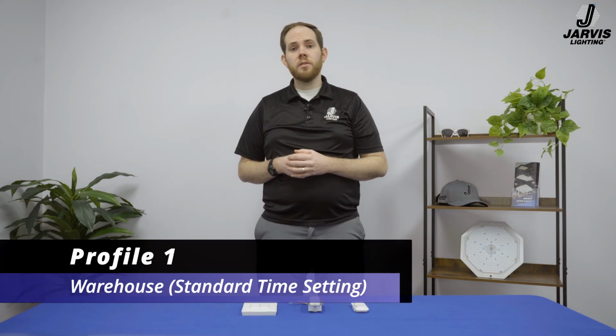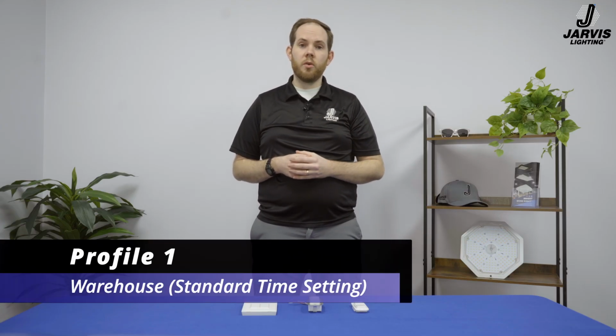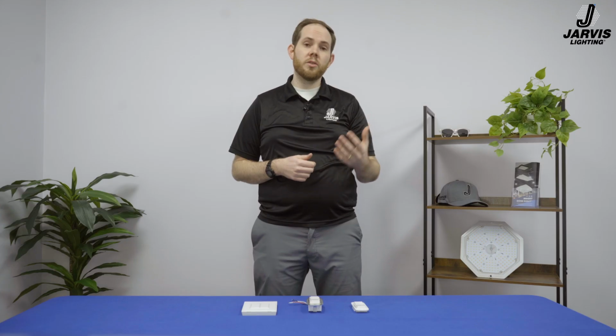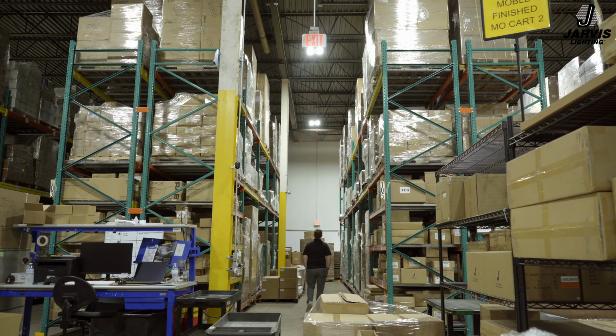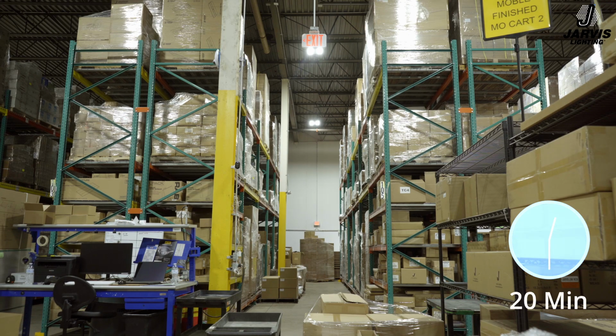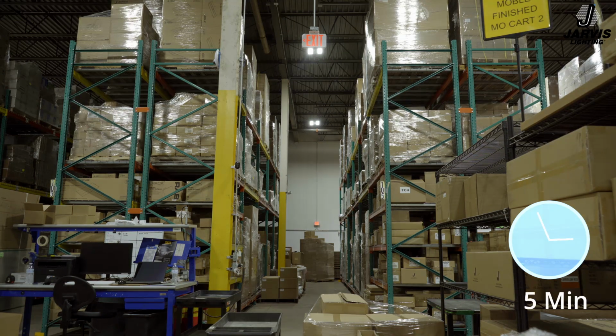Our first profile is the Warehouse Standard Time Setting profile, which is commonly used in warehouses and industrial facilities. This profile can utilize just passive infrared sensors, or PIR sensors, or a combination of PIR sensors and wireless control modules, or WCMs. When a PIR sensor detects motion, all of the fixtures in that particular zone will turn on at 100% brightness. After 20 minutes with no motion detected, the fixtures will dim to 50% brightness. And after another 5 minutes of no motion detection, the fixtures will turn off.